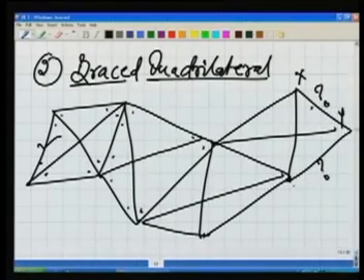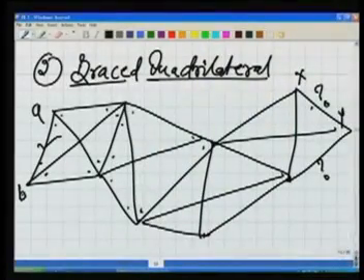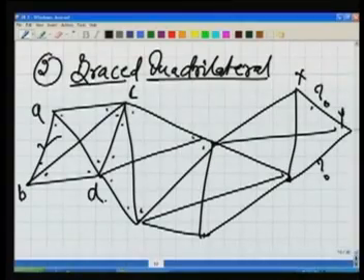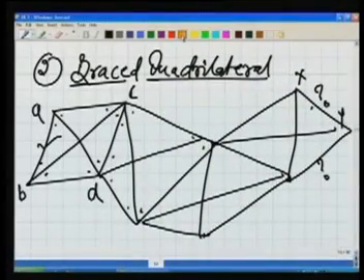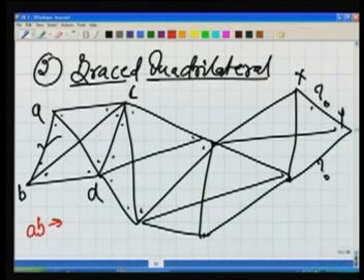So this kind of figure gives you the flexibility of doing the computation from multiple routes. Now how is it so? If you look at this, we have line AB, which is the base length which is measured, and you want to determine the line CD. In order to compute the length of line CD, number one route, I am drawing in red: we can start from this last triangle, starting from AB, I compute, let us say, AC.